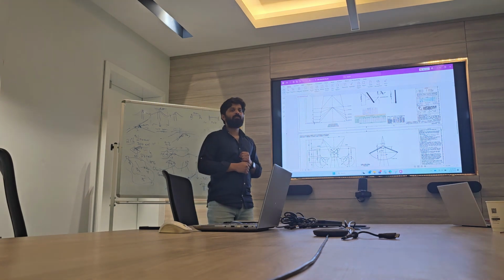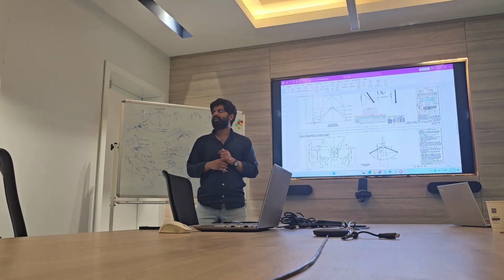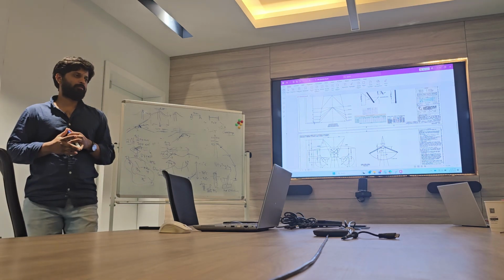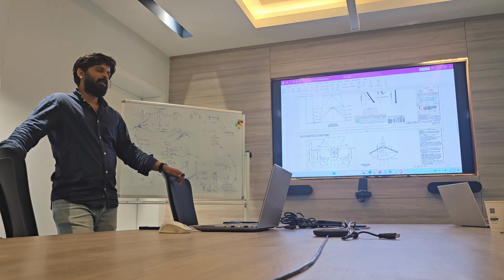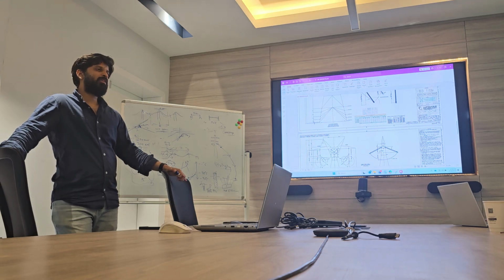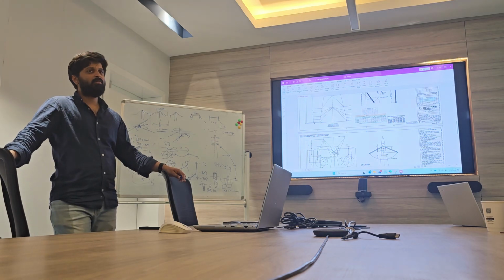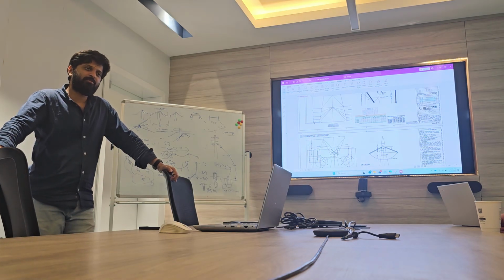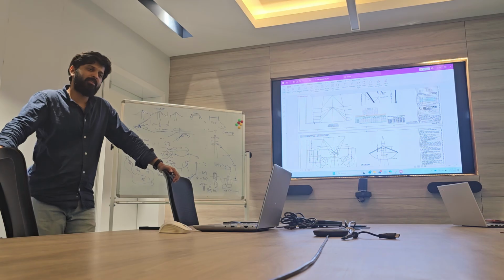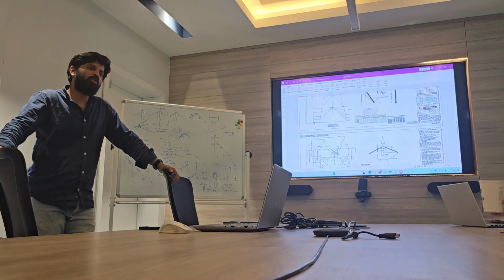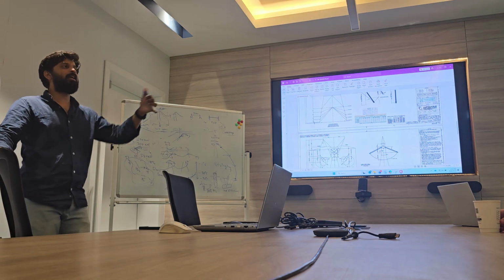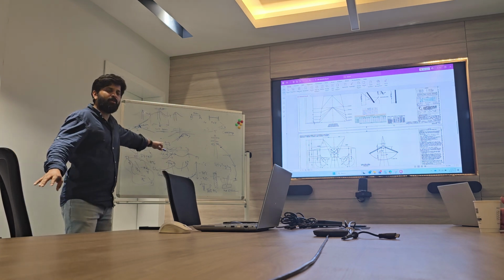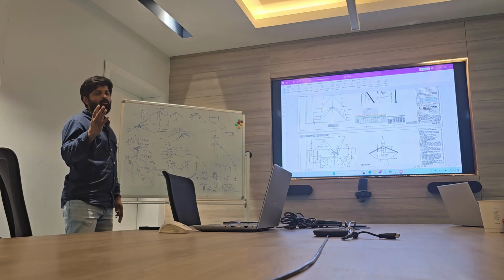Now why do I need an angle tower? What is the use of an angle or tension tower? To be able to deviate the line, and to handle the load. What is the difference between tension tower and dead end tower now? I told you what a tension tower is. Tension tower, we use it for the load in transverse and longitudinal, and also for the line deviation. The longitudinal load will be front and back. What is dead end? Same as tension tower, but load only on one side.